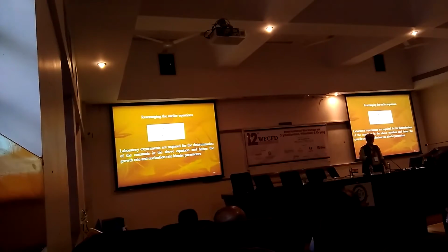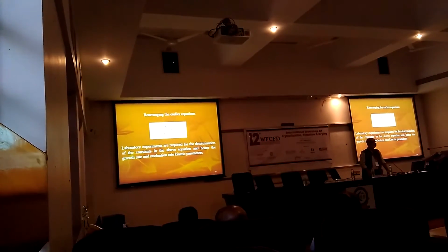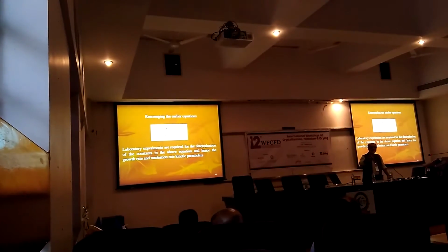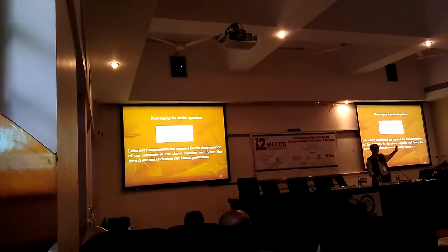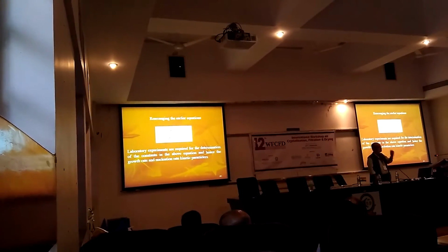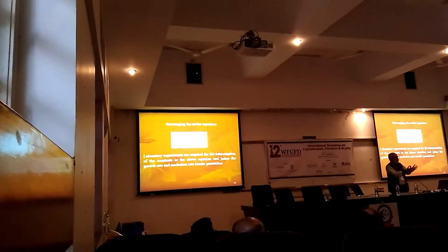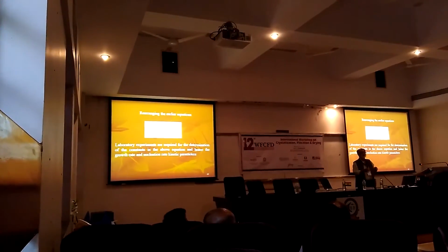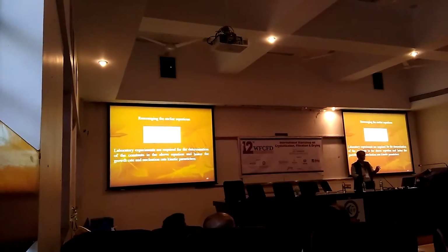So now there are two stages. Let us say, as Mike said, that 90% of the people do not have the solubility curve itself. I would say even if 90% of the people have a solubility curve, they have never experimented with it and made an attempt to obtain nucleation and growth kinetics. If we have a solubility curve, and we have the nucleation and growth kinetics with exponents m and n, we have all the necessary information needed for the proper design of a crystallizer.